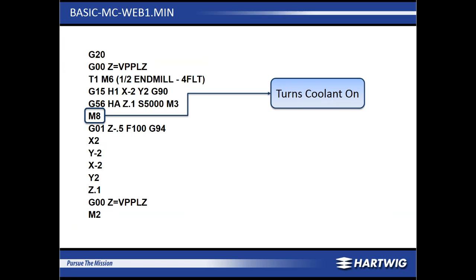So after I've brought the tool to the top of the work, I'm turning on the coolant. Now, this is another personal preference of mine. In a higher production atmosphere, you might want to kick your coolant on before you retract to the top of the work, because you might want your coolant flowing before your tool gets anywhere close to the part. I myself like seeing the tool get to the part before everything gets splashed with coolant and makes me unable to see what's going on.